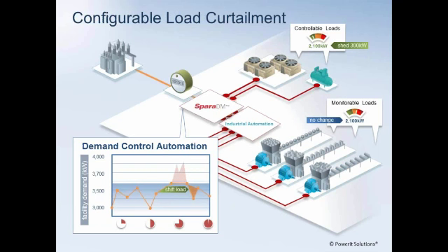So the loads that are just being monitored and non-controlled, if they coincidentally come up and reach a full peak simultaneous with our induction power supplies, we could dial that induction power supply back for a couple minutes. Typically what would happen is we would see a large peak load coming in because of air compressors loading up. So during the time period when the air compressors would load up, we would dial the power supplies back, the air compressors would unload, and the power supplies would go back to full power.